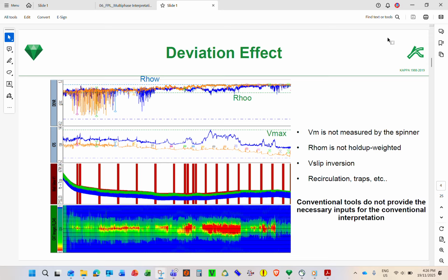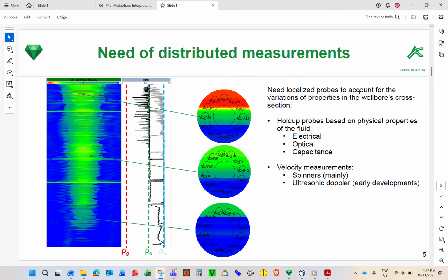Or if you have something like this, water in the sump, water lifts up, but some of the water maybe stays there, like a toilet bowl, a water trap. So water is in the sump, and you need to flush it. So that's why it's not giving you the correct reading.